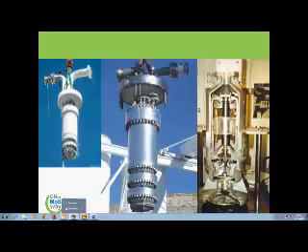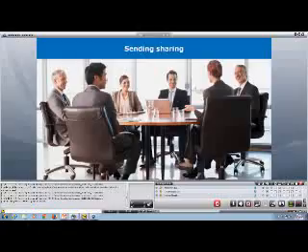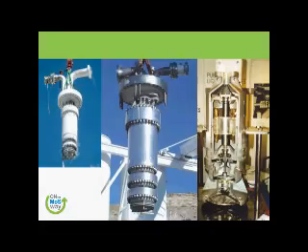So what it is doing, the impeller centrifuges it, and from that it centrifuges the cargo from these fine lines around the tank, in the tank around the pump, and then there is another strainer on the top.